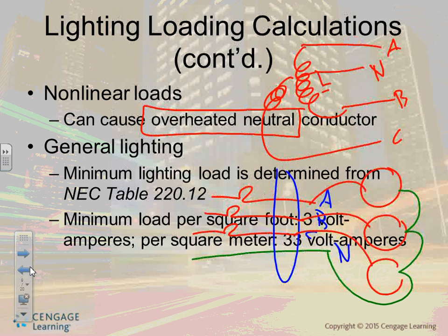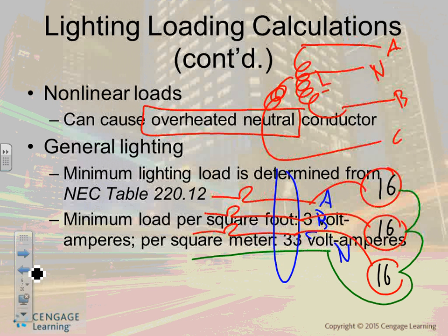And oh, by the way, I said one light here. Why don't you put 16 here, 16 here, 16 here? Each one of these circuits will have 16 fixtures like the one above your head on one circuit. Can you see how many wires are coming out of this? 16 times 3 is what? 48 fixtures, gentlemen. 48 fixtures coming out of a set of wires like these, on 3 breakers tied together.